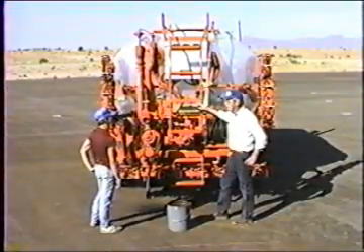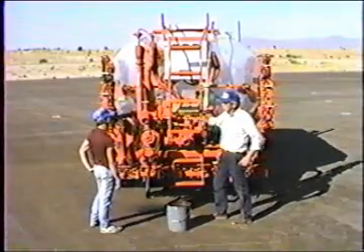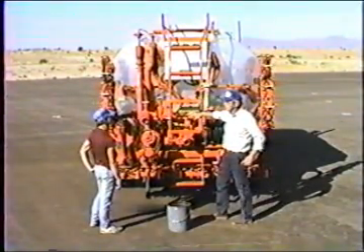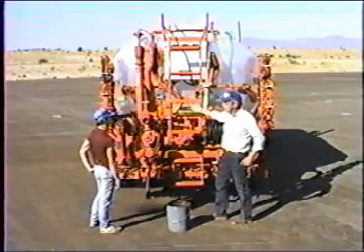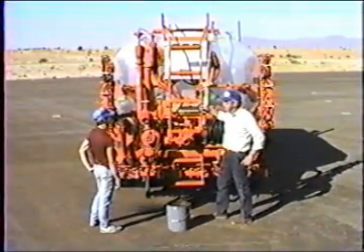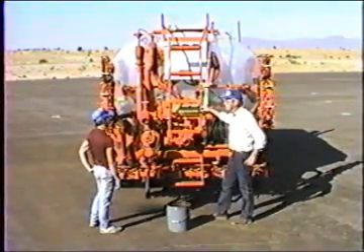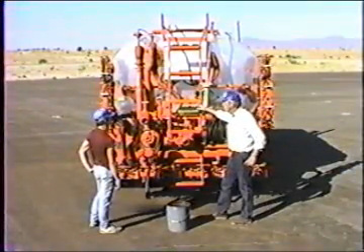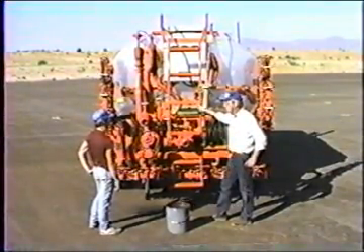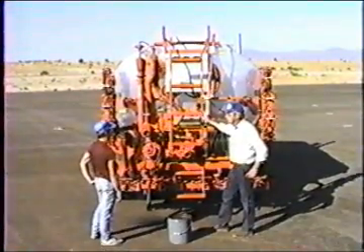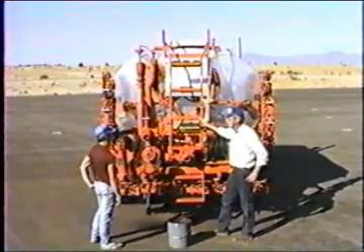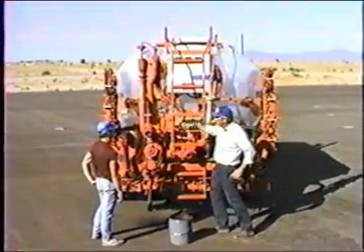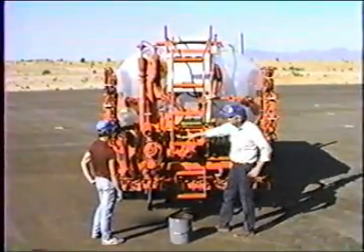Anytime you get out of the cab of the truck, in the same motion that you set the brake with, be sure the master switch is off. If you're out of the truck, it should always be off. This is especially important when we go to clean the truck out. Set the brake, master switch off. Now put the pump into the forward direction. On this computer truck, we're going to put it into manual and put it on full speed forward.